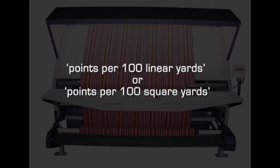In general, the acceptable level of points per 100 linear yards or points per 100 square yards is different for different fabric types. For example, for cotton twill or denim, 28 points per 100 square yards for an individual fabric roll, and for all synthetic fabrics it is going to be 20 points per 100 square yards for an individual fabric roll. The fabric defects are classified again as major and minor defects. It depends on intended end use and also the type of fabrics. Sometimes the minor defects may also be treated as major based again on the end use and the type of fabric that is used.